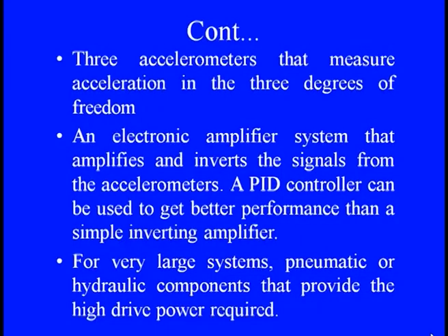We can even use an electronic amplifier which amplifies and inverts the signal from the accelerometer. And sometimes we use a PID controller, which can give better performance than any kind of simple inverting amplifier. So, there are various things which we are going to use.